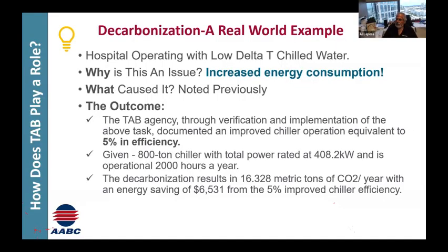Sure. So, presuming that we did correct each of the issues that we had identified on that previous slide and brought the balance into play, the corrective measures improved the chiller's efficiency, say, by 5%, as in the example here. And that's a very, very achievable number. If you remember the review that I did earlier with those three-way valves, that's a lot of it. It's different projects, but that's something you would pick up in the design phase if that's where you were working on a new project.